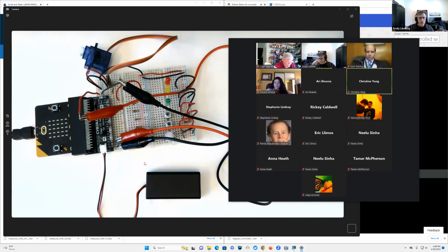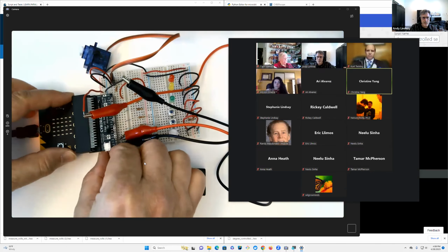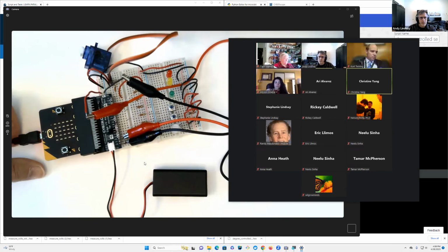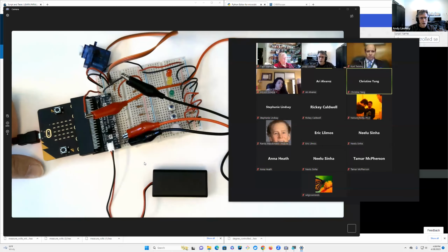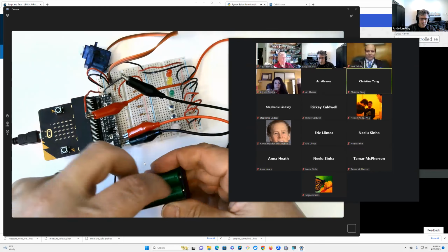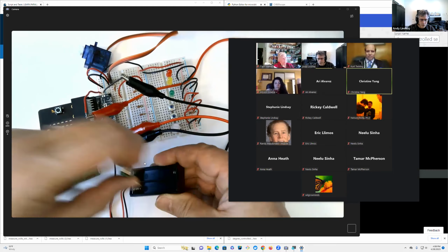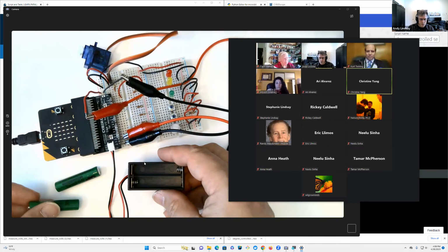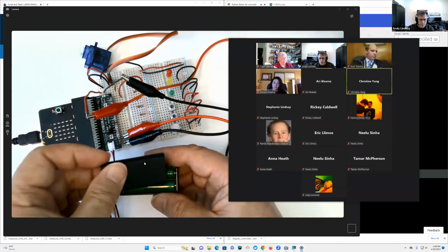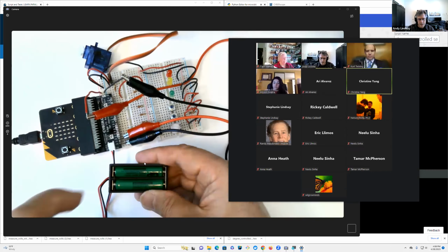And then another question came up during the break about how to remove the JST, Japan solderless terminal plug from the socket on the breadboard, or on the edge adapter, after plugging it in. It's really difficult to pull it out. So my main recommendation is to just simply leave it connected always and just take out the batteries when not in use. That's really the best way to disconnect your batteries, is to just remove one or both. It is fair game to just remove one. Then you're not conducting any current through the batteries.